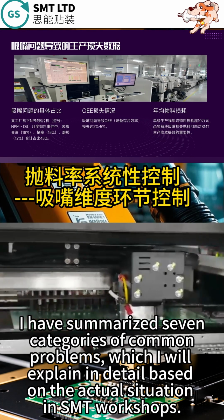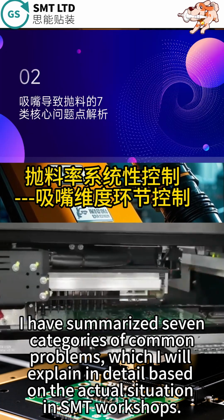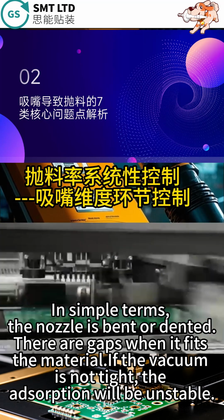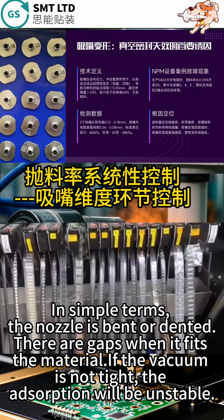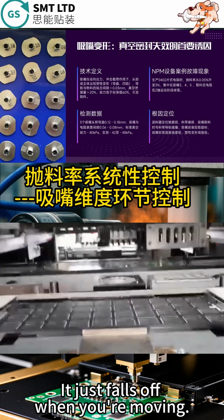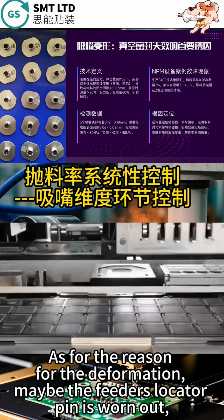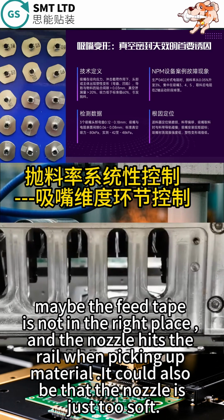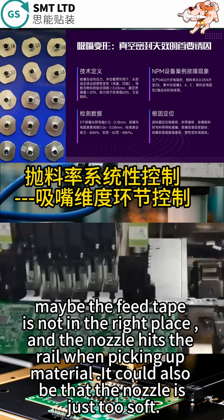I have summarized 7 categories of common problems, which I will explain in detail based on my actual situation in SMT workshops. In simple terms, the nozzle is bent or dented. There are gaps. When it fits the material, if the vacuum is not tight, the absorption will be unstable. It just falls off when you're moving. As for the reason for the deformation, maybe the feeder's locator pin is worn out. Maybe the feed tape is not in the right place, and the nozzle hits the rail when picking up material. It could also be that the nozzle is just soft.